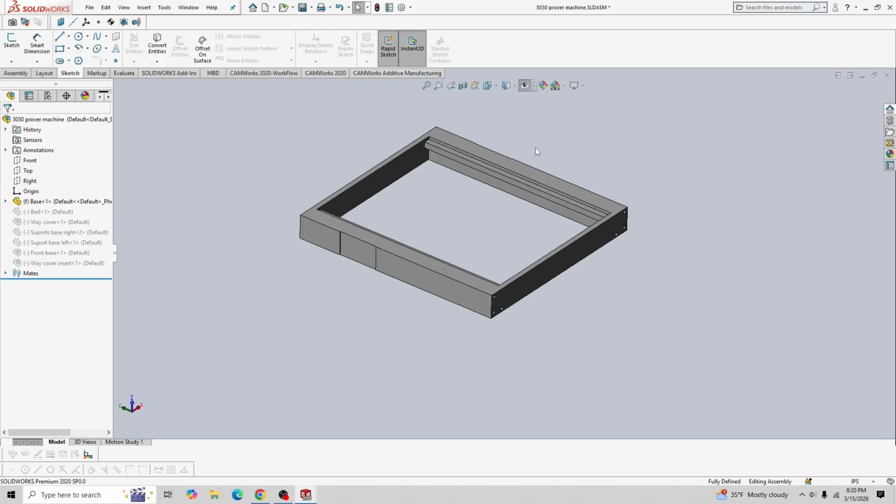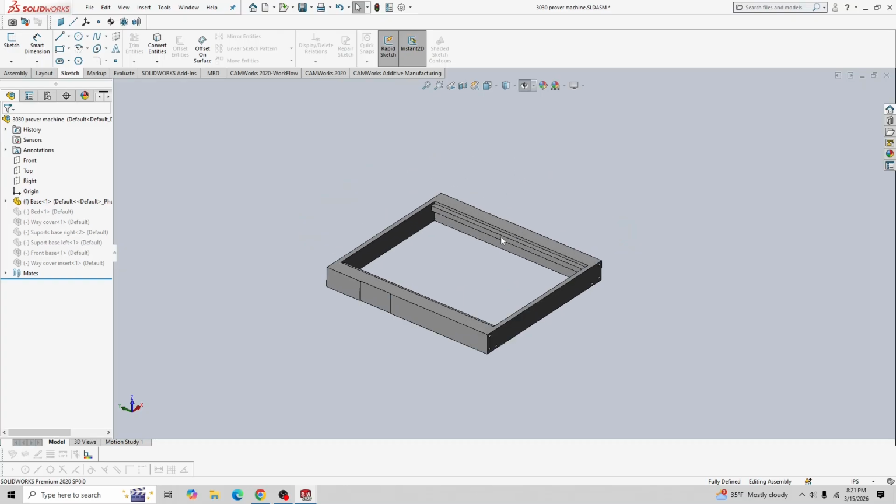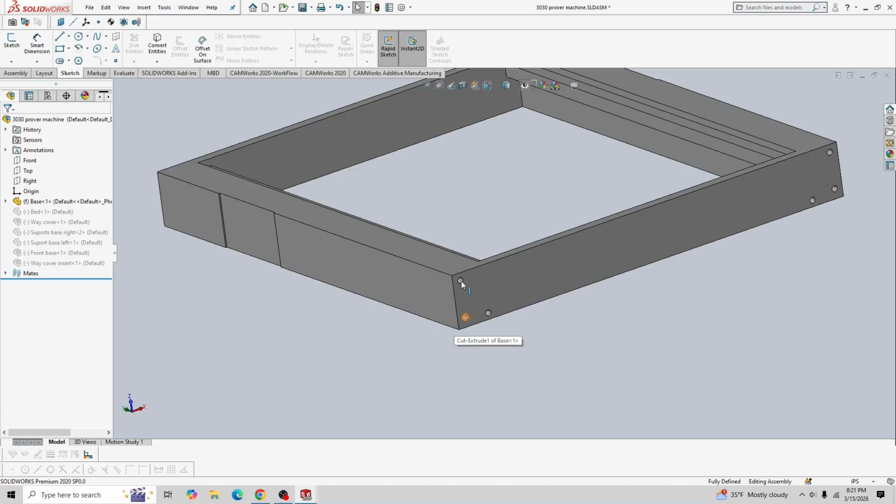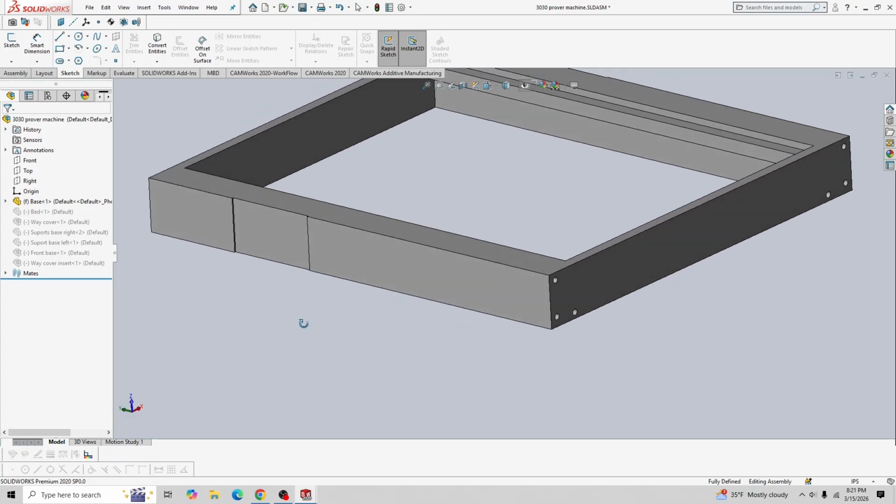And generally you keep stuff like coolant lines and all of that as just little tiny accessory parts. And generally I don't really add that stuff unless I'm going to have basically potential of crashing into something. And mainly that's just in 5-axis where I will do that. But basically what we've done is we've added some holes here, and I plan on using these holes to attach stuff to. So that's why they're there in this instance.